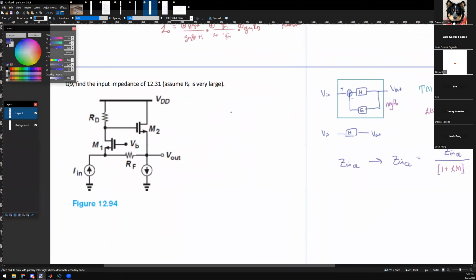Big, right? Big. No. Let's see, small. Z out, let's see your table. Small. Yeah, so 0. But why? Because this guy will have a V out and it's going to have an equivalent Thevenin. This is R out. So R out is going to ruin my voltage source. This is the ideal voltage source. I want R out to be as small as possible so that I have very good voltage drive capability at the output.